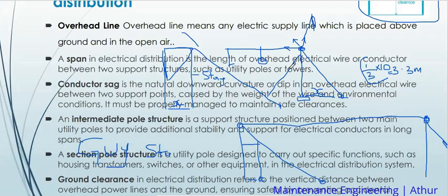If you are noting, you must note that we have an outrigger stay, and that one uses an outrigger bracket. That welded metal you see up, it is at the angle of 90, 60, and 40. It is up, and this stay is passing through it. That is called an outrigger stay. We have a normal stay, and we have a guy pole or a guy stay. That is the one that we put inside in order to support the pole in case the other options fail.